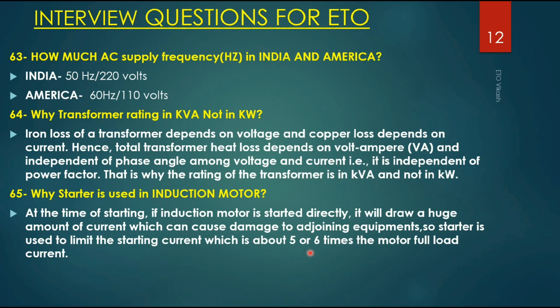If we do not use a starter for a higher rating motor, it will draw 5 to 6 times the current. For a smaller motor it is okay, but for a higher motor the winding as well as the cable will get overheated and damaged, because the heating effect is I squared R t.